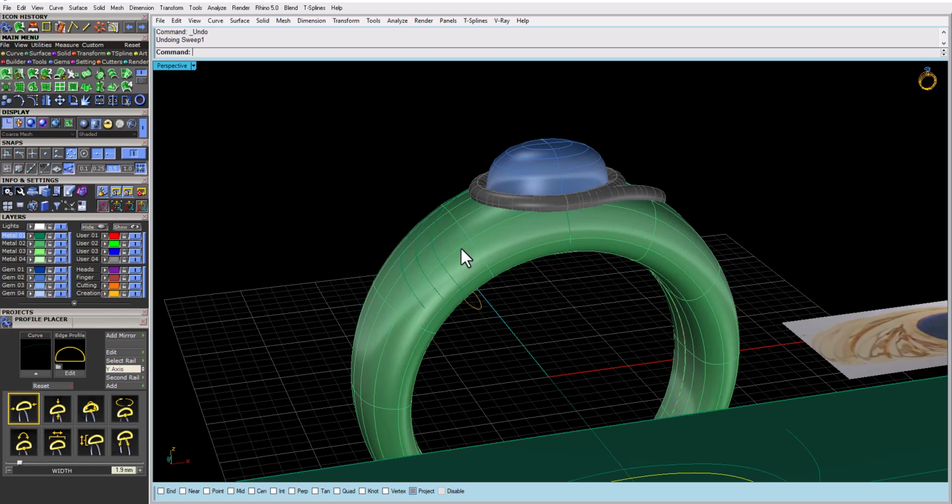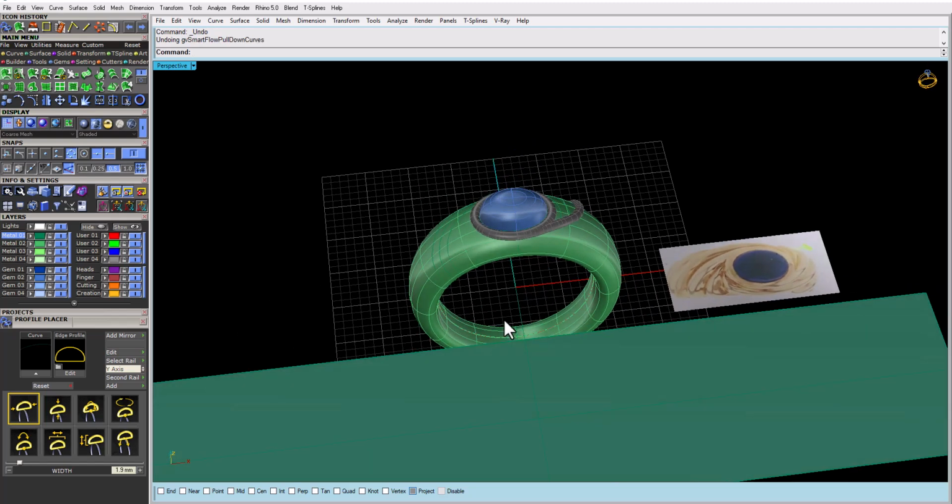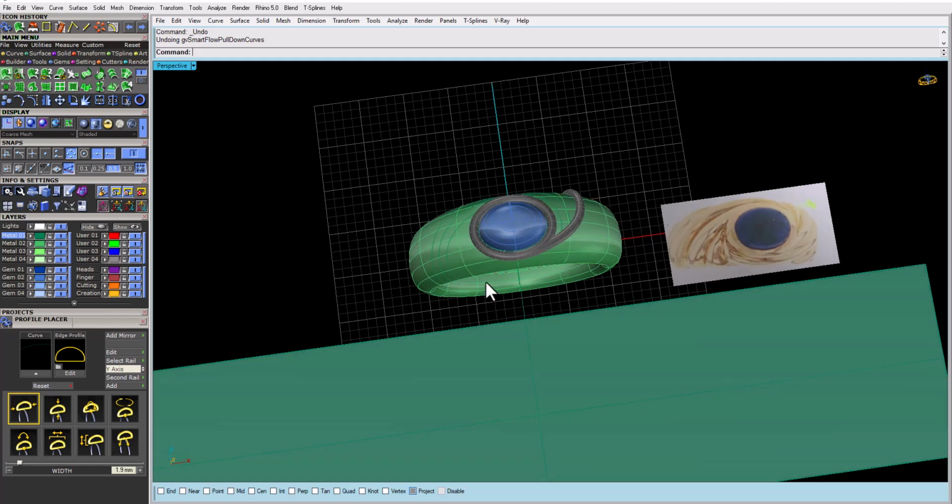Okay, and in case you face a problem with sweep one, because I'm sure here sweep one will not exactly help us. So what I would do here is, once I have my pipe on top, I'm going back, I'm doing undo, because it's not going to be easy with the smart flow, because it's a stretched surface. Okay, it's not flat, and the results are going to differ.